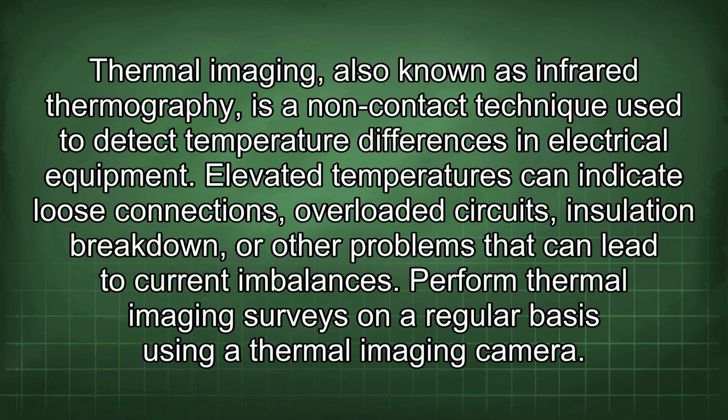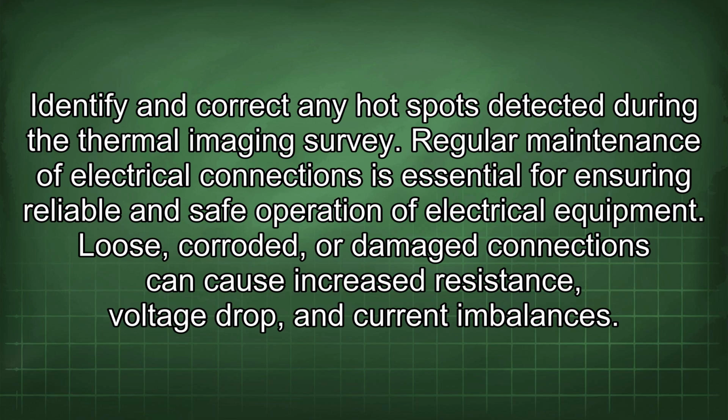Thermal imaging, also known as infrared thermography, is a non-contact technique used to detect temperature differences in electrical equipment. Elevated temperatures can indicate loose connections, overloaded circuits, insulation breakdown, or other problems that can lead to current imbalances. Perform thermal imaging surveys on a regular basis using a thermal imaging camera. Identify and correct any hotspots detected during the thermal imaging survey.